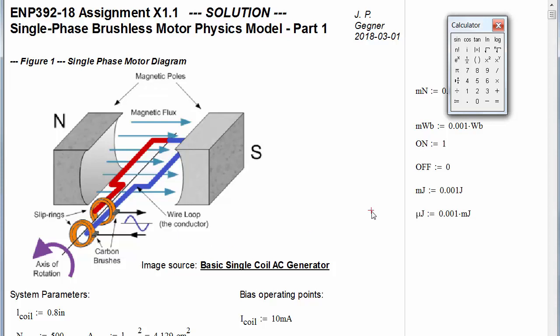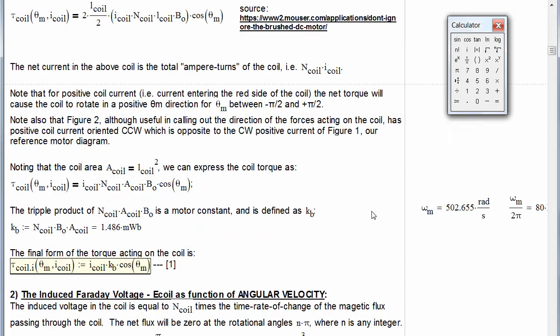What results from that is if you have a positive current and a positive voltage, the product is a positive power, and that power is interpreted as power that is being delivered to, or absorbed by, the element. So passive implies that we don't expect to get any net energy from this device. We plan on delivering net energy to this device. Of course, a motor like this can act as a generator or as a motor. We're using it as a motor, so it's appropriate to use the passive sign convention in this case.